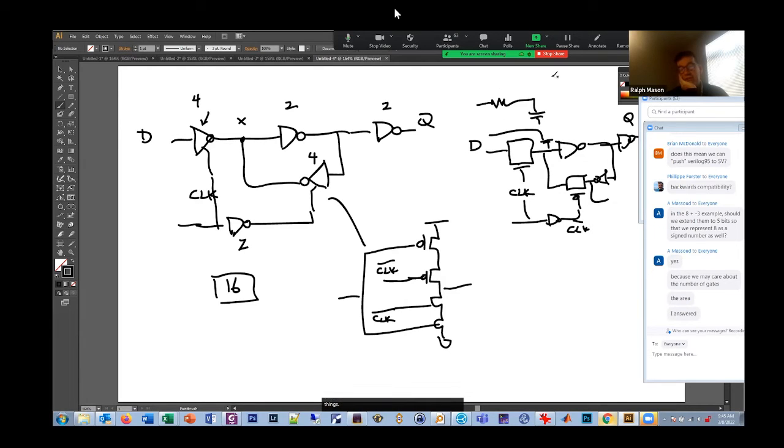The delay: it adds delay going through this RC, and the timing of it, like the rise and fall times, will vary depending on this R value. Whereas coming into this gate right here, it's going into these two gates, really high impedance. And so that means the timing for this flip-flop is much more well-defined. So that's one drawback of using a transmission gate instead of a tri-state buffer.